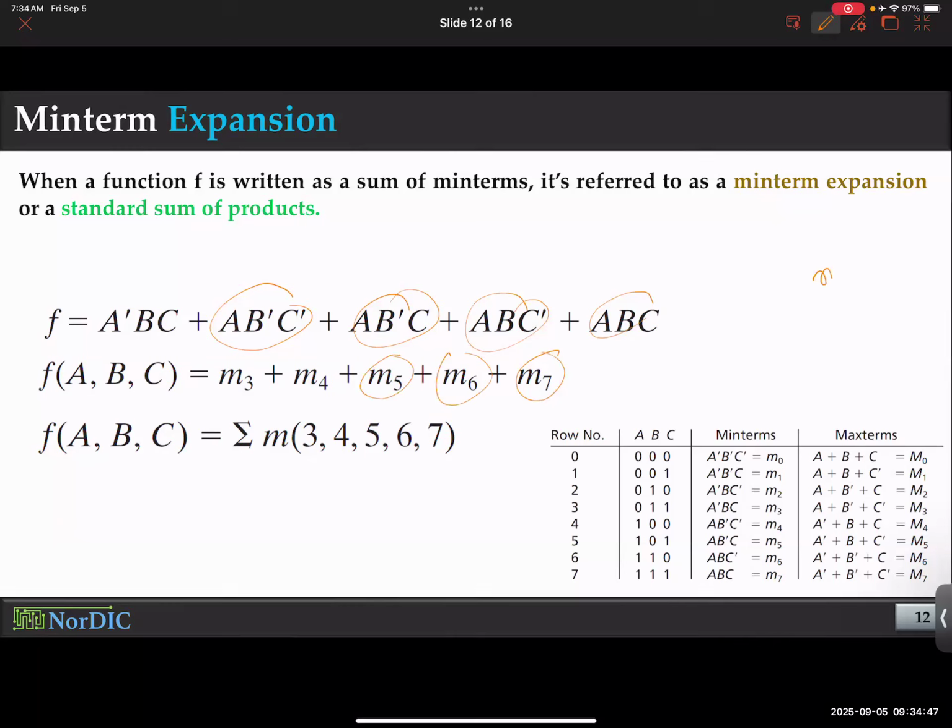And remember, M5 is always going to be this one. You cannot just randomly name anything M5, because these are organized in increasing order, corresponding to the binary combination 101. 101 represents 5, so this min term represents 101, essentially. Does that make sense, folks?